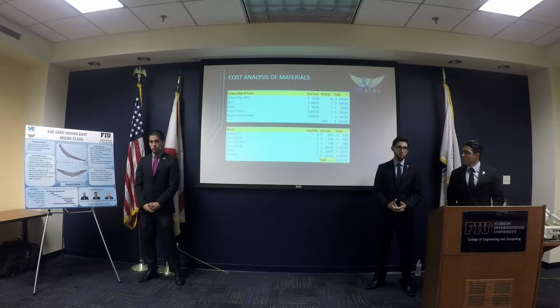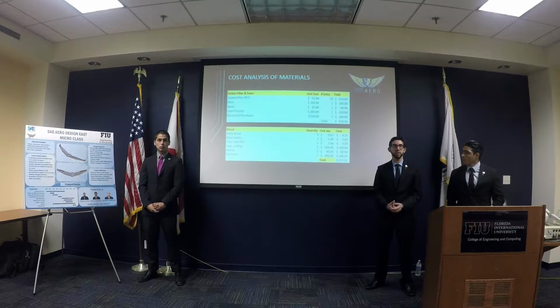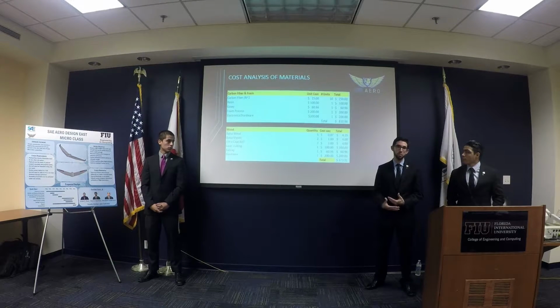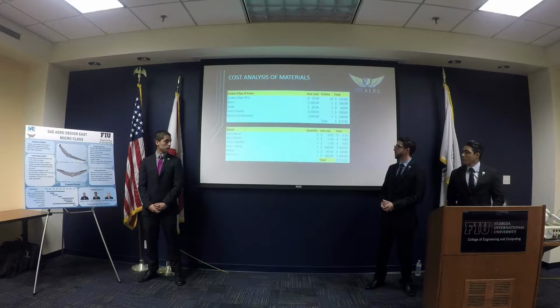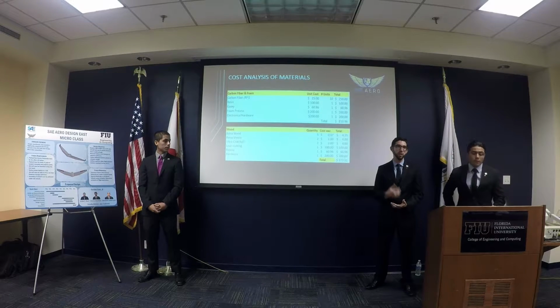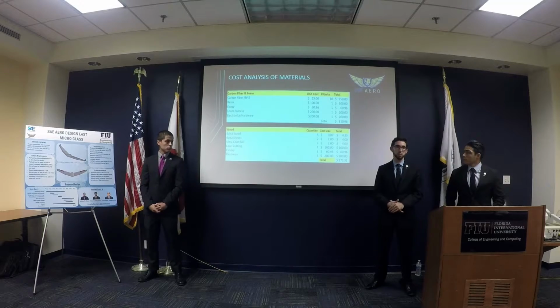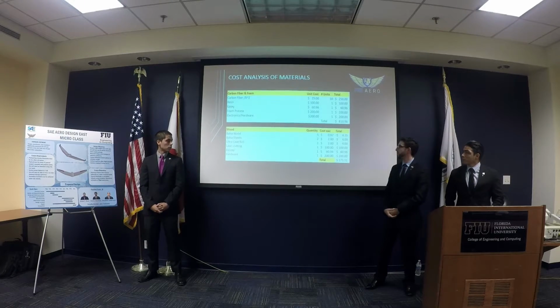If we were to go with composites, it would bring the cost up to almost $800, $900, depending on the fiber that we use, fiberglass or carbon fiber, and the processing, if we want to use a mold, or foams. There are too many factors, realistically speaking, so we just projected the cost for one plane. Naturally, if you were to bring this to a more manufacturing world and make it a mass production endeavor, then the cost will go down, especially with the materials and the process.